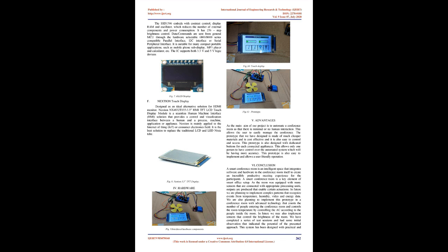L293D motor driver shield. The L293D V1 motor driver shield has 4 full bridge motor driver channels and can drive up to 4 DC motors or 2 stepper motors. It fits Arduino Uno or other Arduino with compatible I/O pins. The L293D V1 motor shield can drive up to 4 DC motors at voltages from 4.5 to 25 V and at currents of up to 1.2 A peak, 600 mA continuous, per motor with speed and direction control.